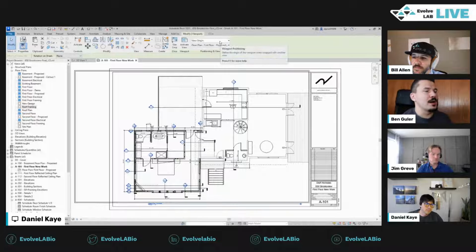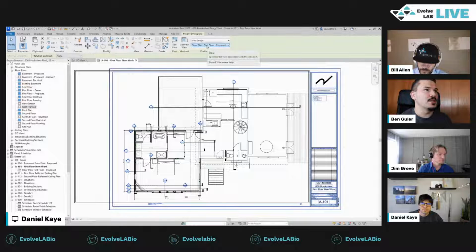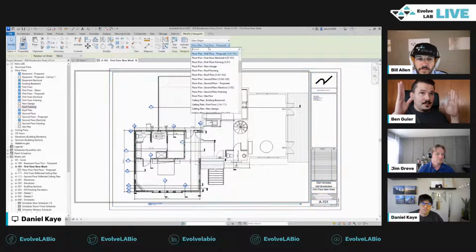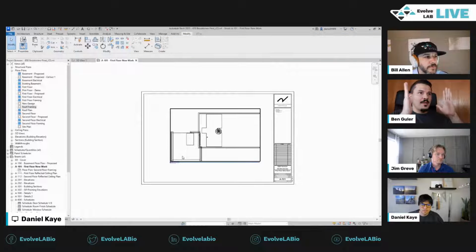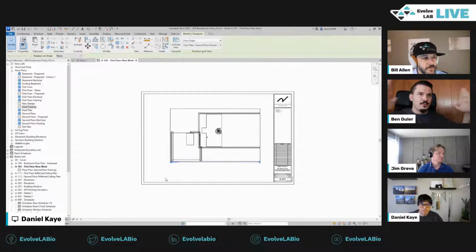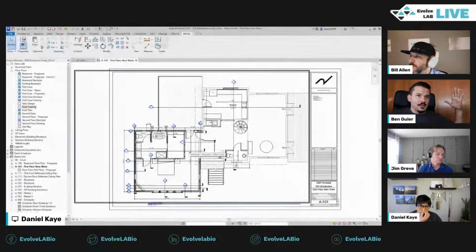Basically, if you swap this view for a basement level or upper level view of this, if you keep the origin, the model coordinates will stay in the same spot, so the view won't shift. But if you keep the center, not the view origin, then it will try to flex the view and it will move the model if the view is bigger. Let's say your upper level is longer, so you want to have that still fit on the sheet.